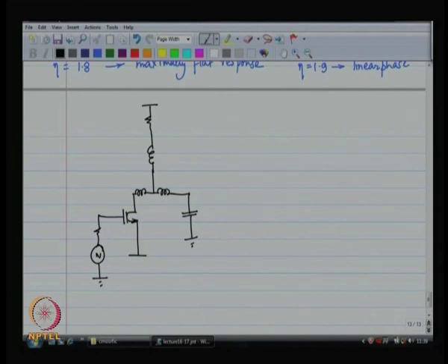Now, why would this perform even better? Let us quickly go back to our original. Our original was this, right. This was the very first circuit. So, when you apply a pulse at the input, suppose you apply a step at the input, initially no current was flowing through the device, now current will have to be established. So, the current also should follow a step. So, the current through the device is also going to follow a step, but the voltage at the output you want that to follow a negative step.